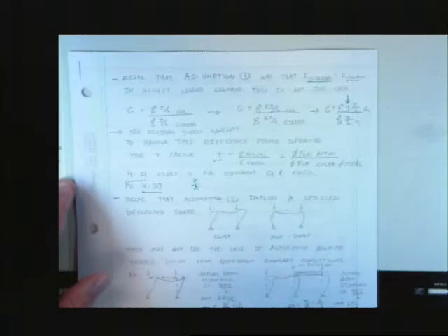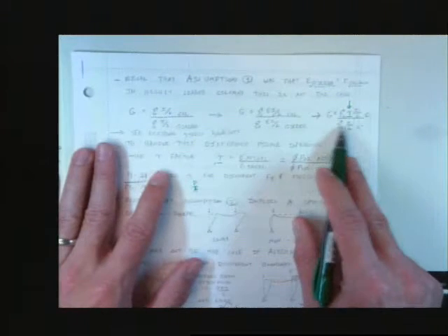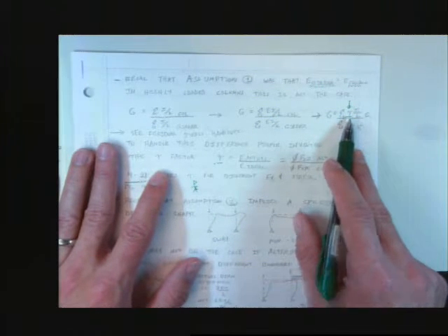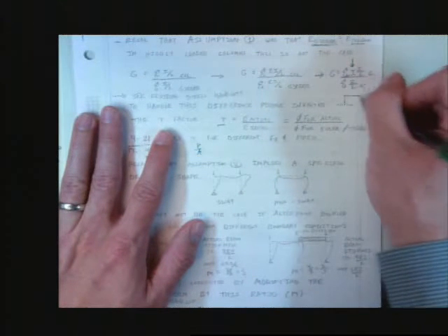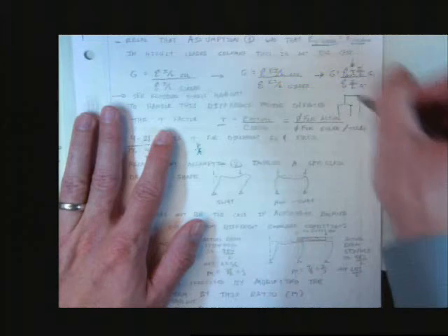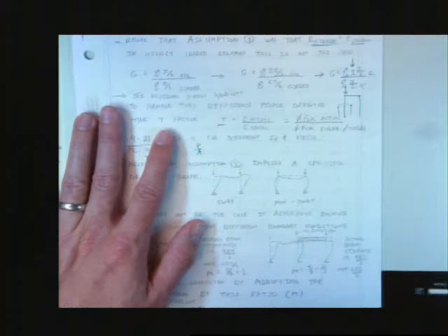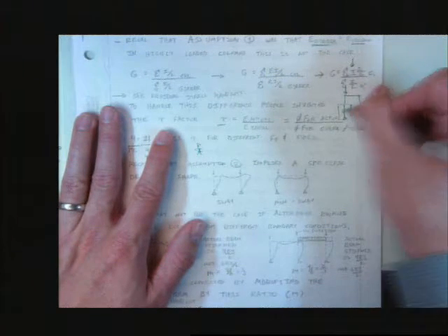Does that make sense? All we've done here is we've modified this G. We've just modified it by adding a tau factor to the numerator. For what you know now, you'll use a tau factor on every column. So if I have a joint here, I have some structure. I don't like that structure, so I'm adding another column there. Let's say I have a load here, and I'm looking for the K of this column.